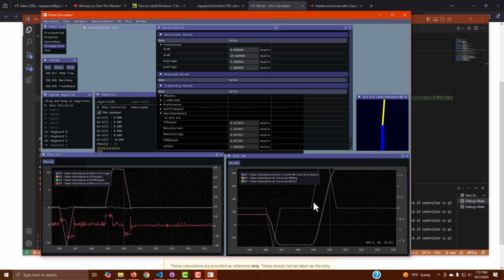You can see the trapezoidal velocity profile much, much clearer here because it's such a long move. Now we're limiting out. Our acceleration got us up to that 1.8 radians per second max, and then it holds there. So all in here, it's all going up at 1.8 radians per second. And then the acceleration makes it smooth on the edges. And so we can see that in here. And so we're testing, our control's working. And if you have your own way of doing your control, you can test it here and see if it's working.